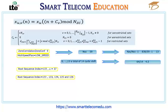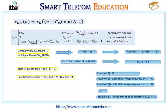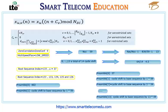Then the 64 preambles are generated as follow for our example. The first preamble will use the base sequence, U 37. The second preamble equals cyclic shift to base sequence by 1 times 59. The third preamble equals cyclic shift to base sequence by 2 times 59. Till the 14th preamble, PRACH sequence 13, equals cyclic shift to base sequence by 13 times 59. Then, to use the next root sequence index, 123, and the value of U is 802, to generate the next 14 preambles.